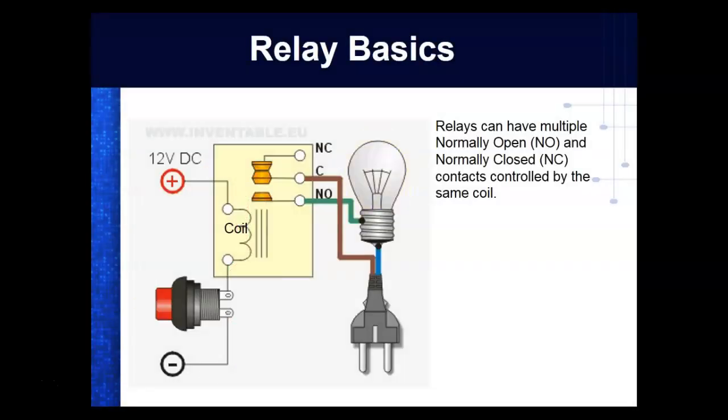So this would be a relay. So a relay comes in, we have a push button, we push the button, generates the current flow through the coil, creates a magnetic field, opens and closes contact. So the top is what we call a normally closed contact. We don't have anything wired up to it right now. And the bottom would be normally open. So normally closed means if this button's not pressed, the top contact's going to be closed. The bottom contact will be open. I press the button, and the bottom contact closes.